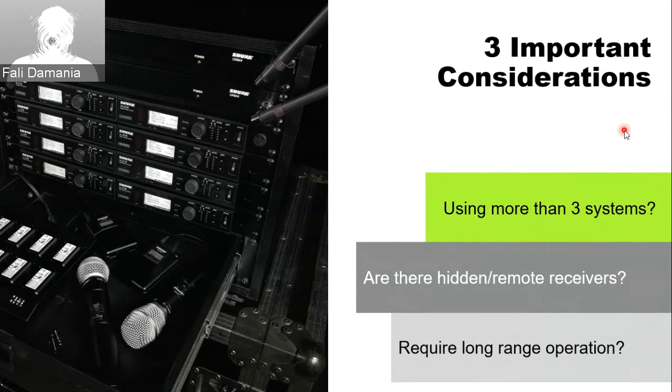Because for any of you that came to the previous webinar, which was about types of antennas and placements of antennas, the one thing that we saw there is that at all costs you want to avoid a situation where you have an antenna farm. You don't want all these antennas bunched up together, because each of them interacts with each other, and that basically destroys to an extent the polar pattern that the antenna was designed for. And if you end up destroying the polar pattern that the antenna was designed for, your system's not going to work the way it is supposed to work.